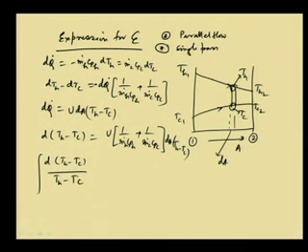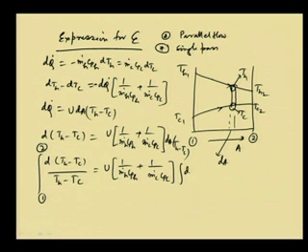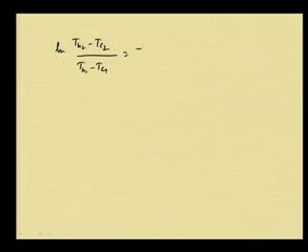Now, we will do the integration from station 1 to station 2, and that is equal to U into (1 by m dot h Cph plus 1 by m dot c Cpc), and then we will integrate these from 0 to A. The area at station 1 is equal to 0 and at station 2 it is A. So, 0 to A, that is the situation. A is the total area of the heat exchanger. So, under this situation we can say that ln of (Th2 minus Tc2) by (Th1 minus Tc1) equals minus U into A times (1 by m dot h Cph plus 1 by m dot c Cpc).